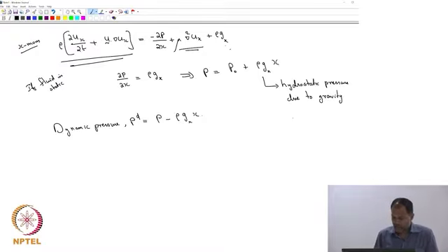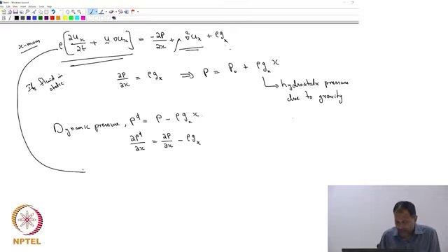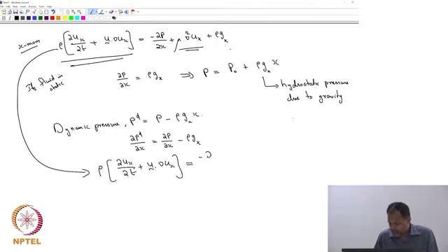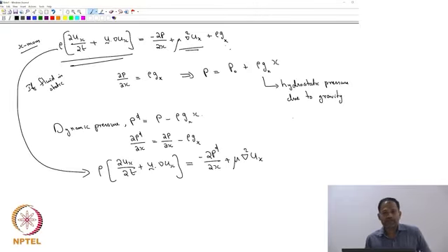Okay. So what is then ∂P_D/∂x? That's simply equal to ∂P/∂x minus rho g_x, and therefore if I look at this equation, I can say that it's rho times (∂u_x/∂t plus u dot grad u_x) is nothing but minus ∂p_D/∂x plus mu del squared u_x. Agreed?